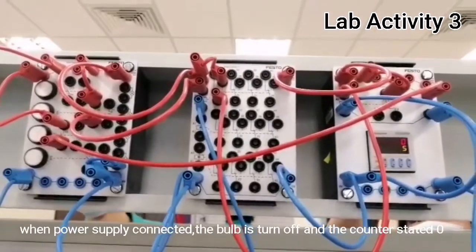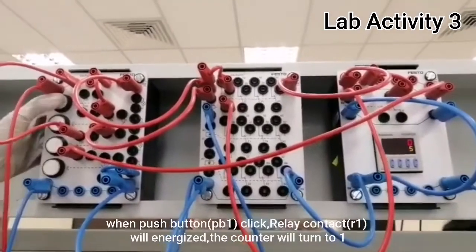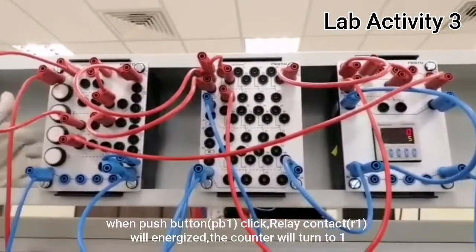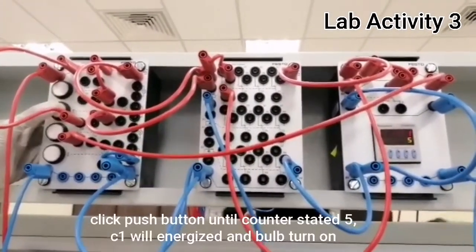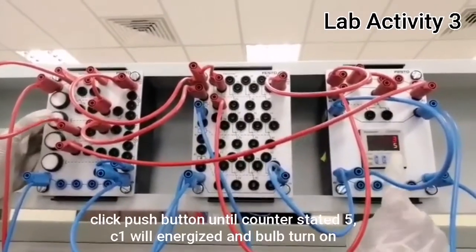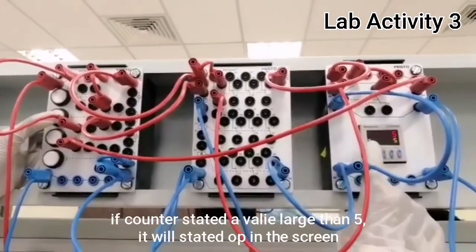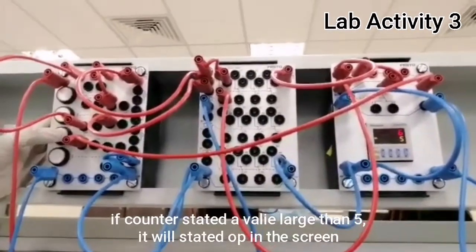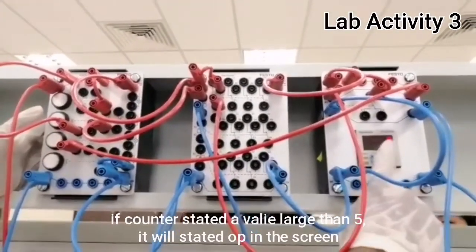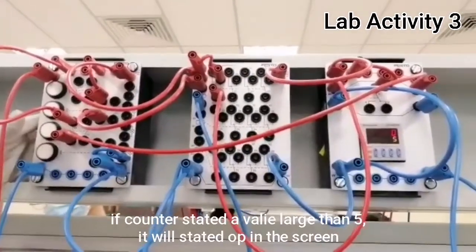When the power supply is connected, the bulb is turned off and the counter states 0. When push button PB1 is clicked, relay contact R1 will energize, the counter will turn to 1. Click push button PB1 until the counter states 5. C1 will energize and the bulb turns on. If the counter states a value larger than 5, it will state OP on the screen. Click push button 2, PB2, to reset the counter.